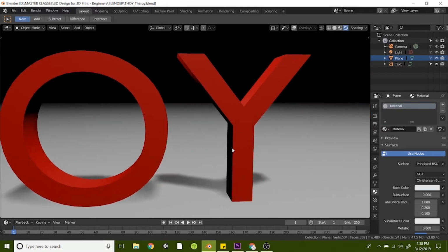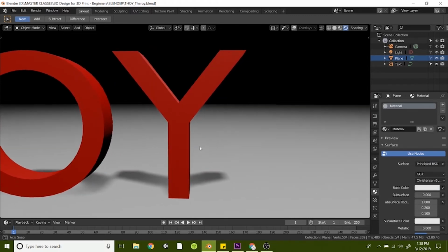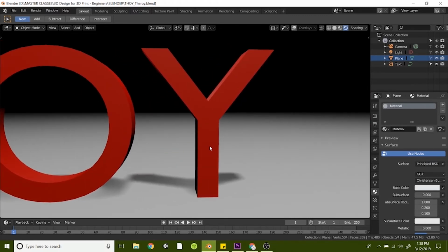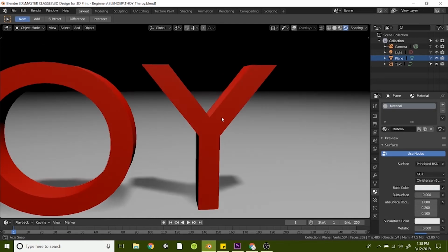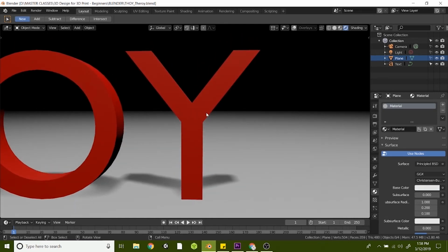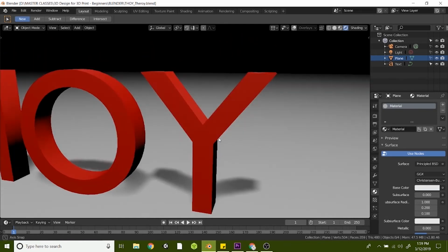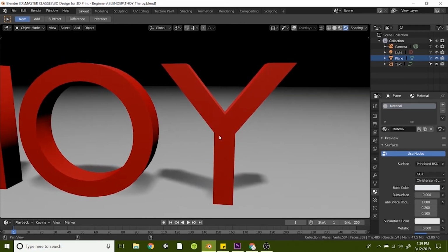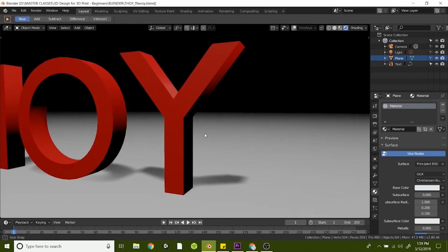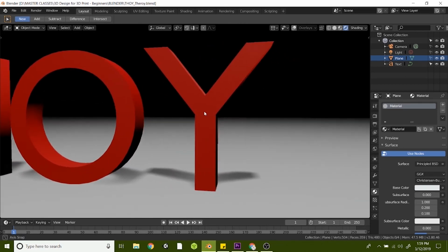And the next is the Y. Now this is to represent 45-degree angles, which you'll hear a lot. So the printer would come up to here and would have no problem building up this Y shape because of the 45-degree angle here. So that would be a clever way that we can add overhangs to our 3D prints by just not breaking the 45-degree rule.